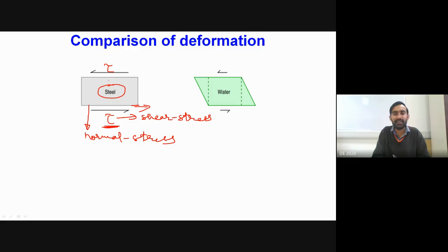to shear stress. So obviously, if I apply shear stress, I will find that it will slightly deform like this. Okay, so this is our original block. When it is subjected to shear stress, we will find that our final block will be something like this. For example, this was its original position, so it has distorted through an angle delta theta upon the application of this shear stress.